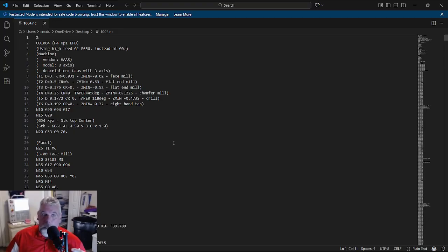So I would have a work stop at the machine, so I load the parts, and I'm going to set it up for production. So if you need to make 100 of these things, it's set up ready to go. So we can probe that XYZ, put it in the middle, get that work coordinate going, and then load our parts against the work stop. And there we go. So we got enough information here to do the job.